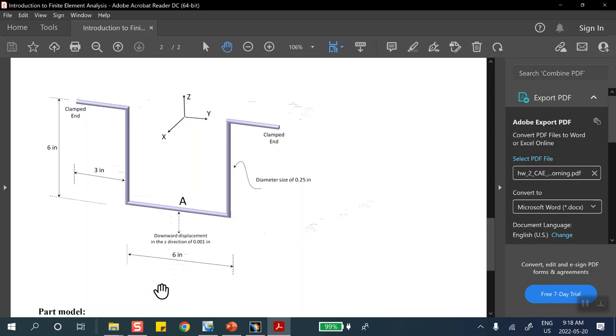But then you have to look at it and say, oh, this is being pushed down, so everything is symmetric on the 2 sides. It is symmetric because this is pushed down. So xz is a plane of symmetry. No translation in y. As soon as you see xz is a plane of symmetry, no translation in y, and rotation, opposites.